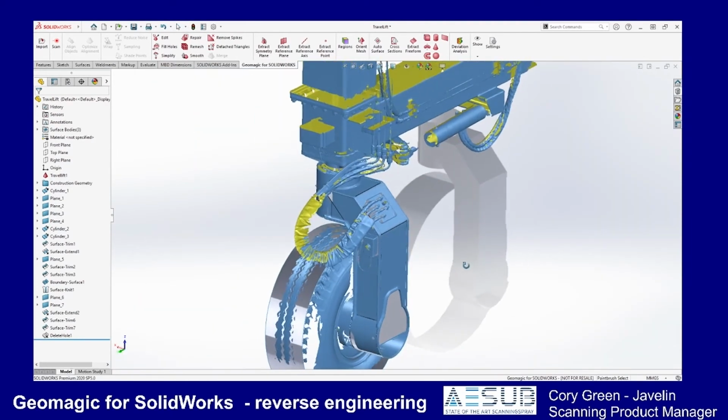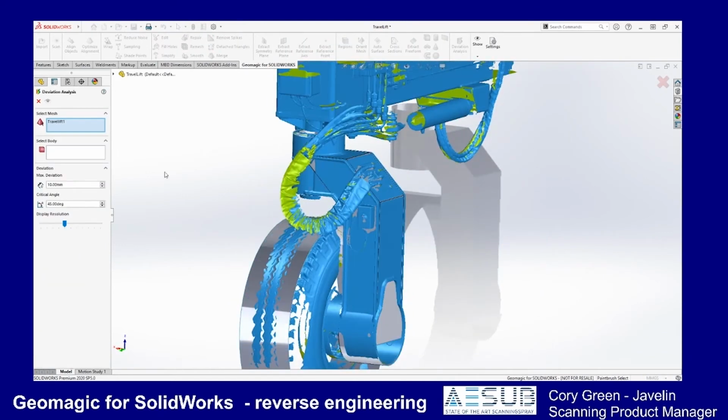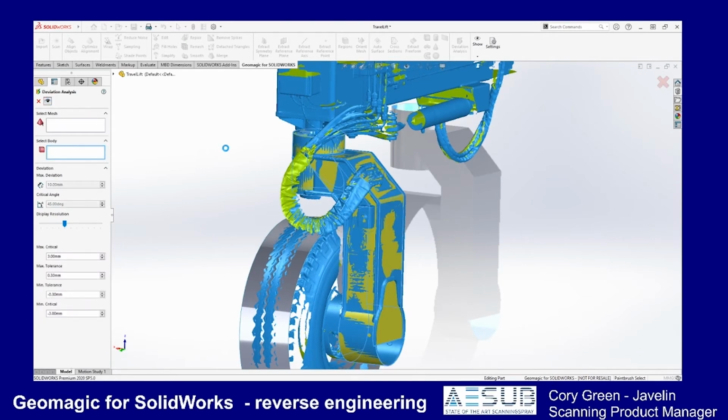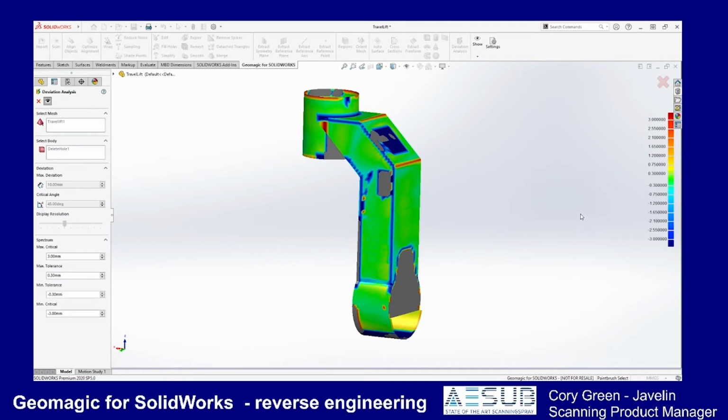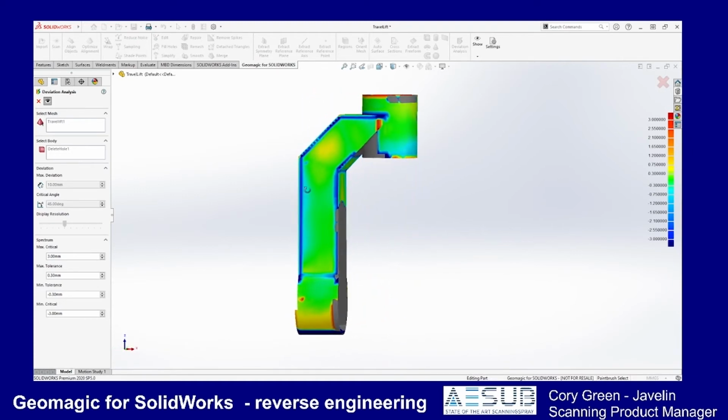Now that we've got that simplified model of the lower leg of the travel lift, let's have a quick comparison and see how accurate we're doing. It's good to check this every once in a while just to make sure we're on the right track. We'll run that now. All right, so we're having a quick look at it. Anything in bright green is within the same space as the model within 0.3 millimeters. So we're expecting most of the planar areas to be pretty good there.